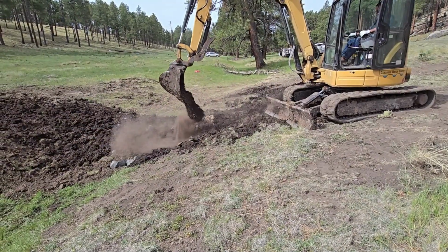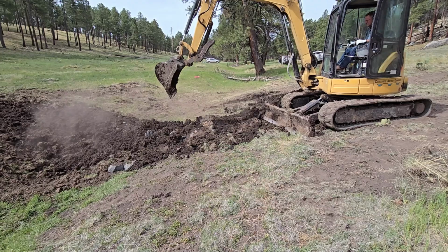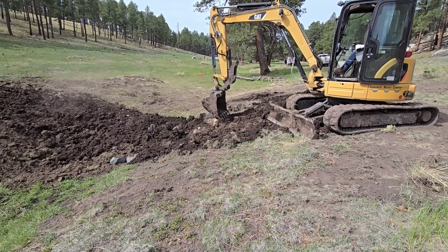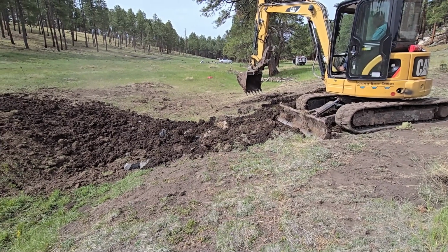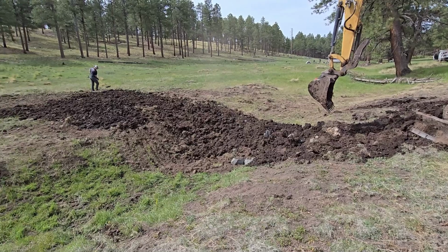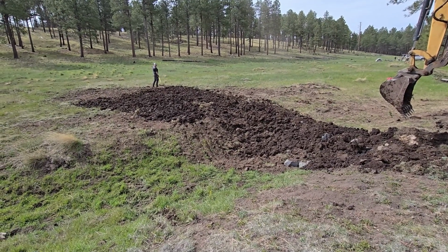Don moves over to the other side of the valley to shape a gradual bank of soil over the end of the rock-filled trench. He rakes and loosens the soil so that water will flow over the buried vertical grade control structure in a sheet-like pattern. Notice how soil has been spread and shaped in the valley so the flow of water will not be concentrated in a narrow channel over the structure.